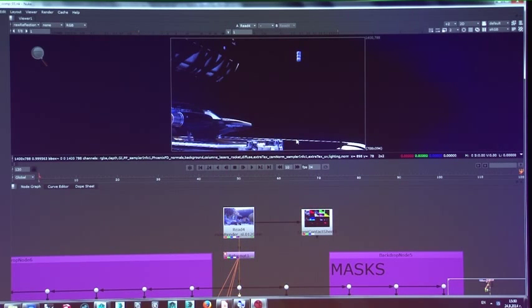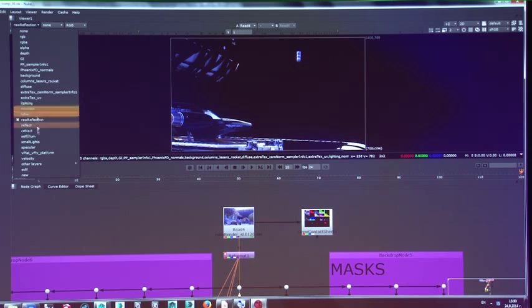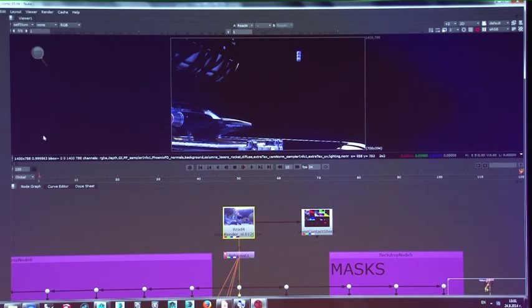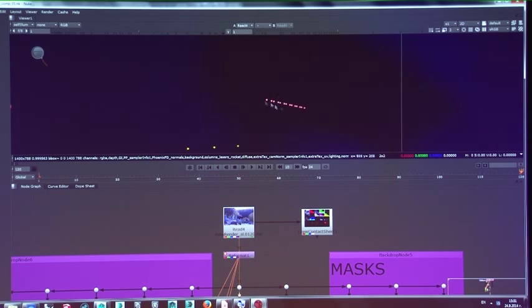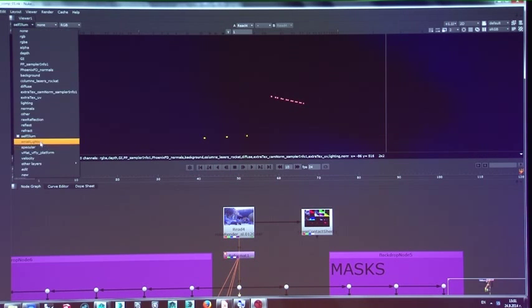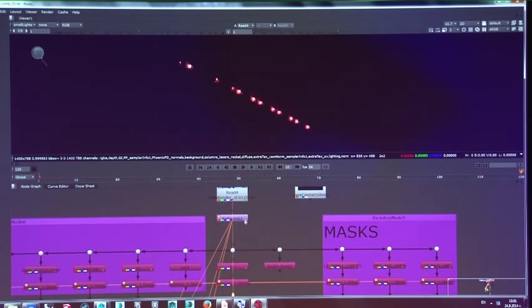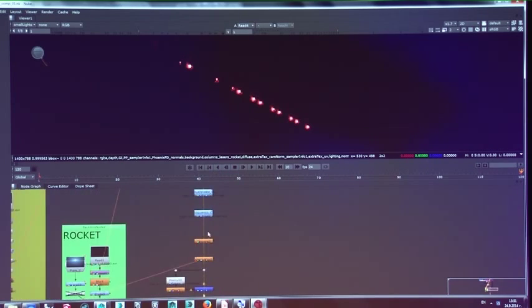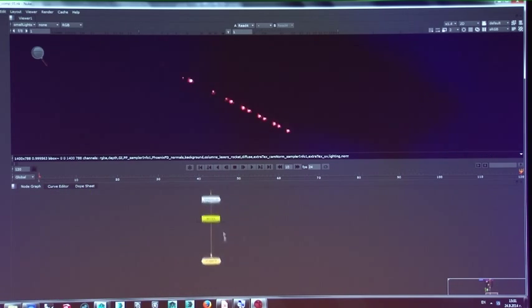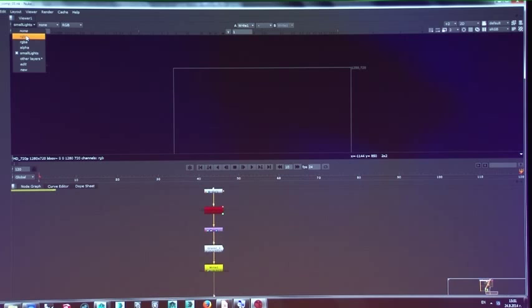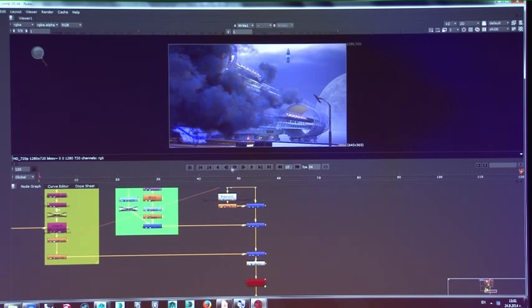One of the passes that I wanted to stress is the self-illumination, which gives me the contribution of all the lights here. However, I have a light select render element which will extract the contribution of a specified set of lights, which can allow me to change these lights later on. And to demonstrate this, let's take a look at the final image. Okay, the RGB. Oops, that's the explosion.